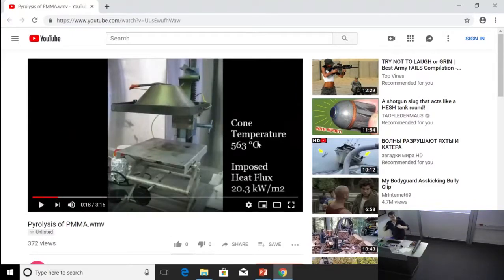Okay, this is a surface. It provides a known, uniform and constant, controllable amount of energy by radiation arriving to the flat surface below. And they put here a polymer that is particularly good for science, not very good for engineering. It's called PMMA, polymethyl methacrylate. It's good for science because its behavior in pyrolysis is simpler, flammable for sure, but simpler. And that's good. Not very good for engineering is because no one uses PMMA, except for the methacrylate chairs with no occurrence of fire, or architects now put them as facades because they like it more than glass. Fine, but it's not a dramatic use of the polymer.